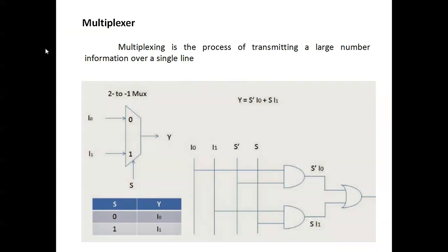So, multiplexer. So far we have seen packages, operators, dispatchers, adders, full adders, and the coding part in VHDL. Now we are going to see the multiplexer 2:1, 4:1, and the demultiplexer side, 1:4. So the coding we are going to discuss.